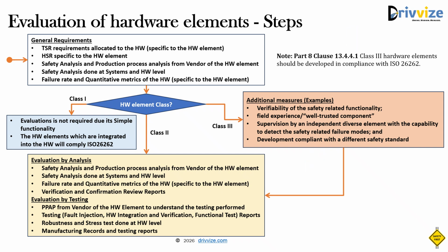Finally, an important note from ISO 26262 Part 8 Clause 13.4.4.1. Class 3 hardware elements are expected to be developed according to ISO 26262 itself. This means the standard does not recommend qualification as an alternative for Class 3 components.